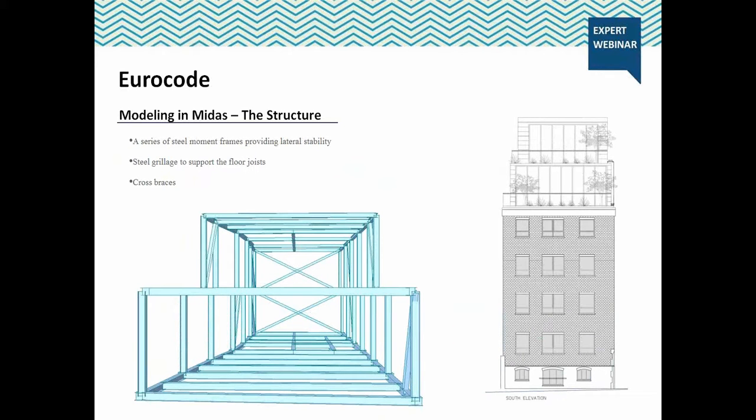The steel moment frames were used to distribute the new loads onto the masonry perimeter wall without loading the existing solid roof, as the strength of the existing roof is difficult to verify. The steel frames were also designed to provide lateral stability when wind loads act on the structure. In plan, we designed a timber joist floor spanning between a series of closely spaced 203 by 203 universal columns as beams. These floor beams are then pin connected to the steel frame.